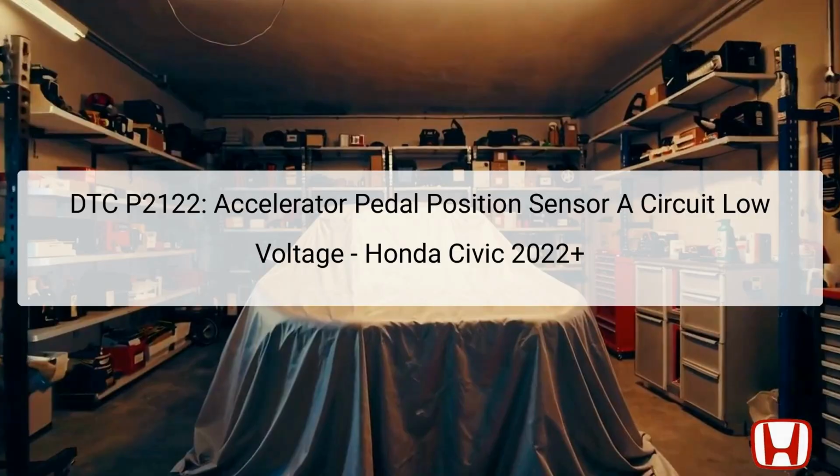The diagnostic trouble code DTC P2122 pertains to the accelerator pedal position APP sensor A, indicating a low voltage reading in the throttle position TP sensor D circuit. This code signifies a problem detected by the powertrain control module, PCM, which is responsible for managing the engine and transmission performance in the Honda Civic.